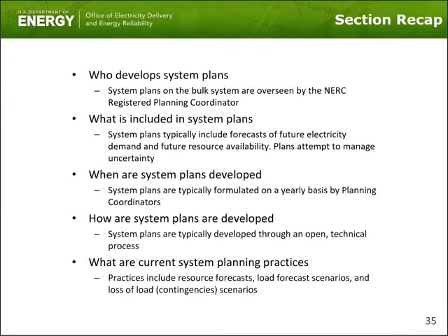However, that does not mean that the entire 100 megawatts of capacity will not be taken if available by the system operator. The percentage of the capacity derate is left to the discretion of the local planning authority, and this capacity derate is most often determined probabilistically using past system performance attributes.